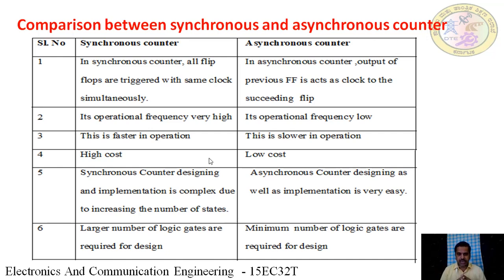In synchronous counter, operational frequency is very high because clock is applied at the same time. In asynchronous counter, the operating frequency is less because the subsequent flip-flops have to wait for the previous flip-flops to change state. Synchronous counters are much faster, asynchronous counters are slower.